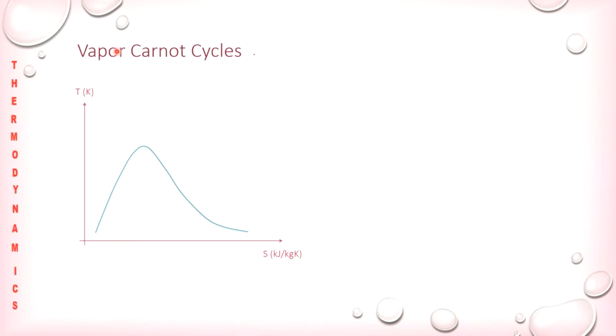Remember, whenever it refers to vapor or steam, you must always include the saturation dome. For gases, you don't have to. Only for a substance which undergoes a change in phase from liquid to vapor. We are not looking at solid, we are looking at liquid to vapor. Anything that exists as vapor and liquid, we have to include the saturation dome.